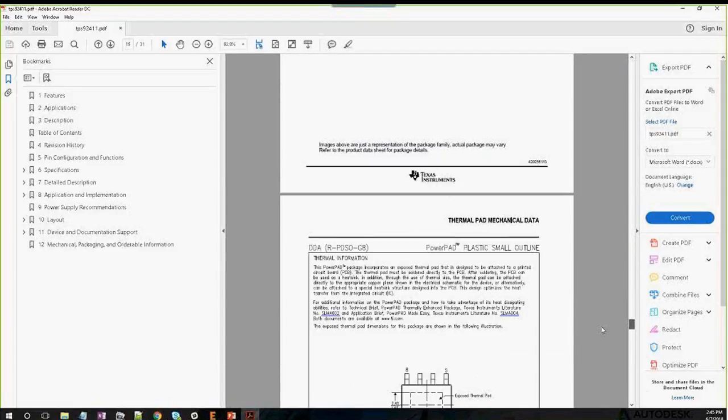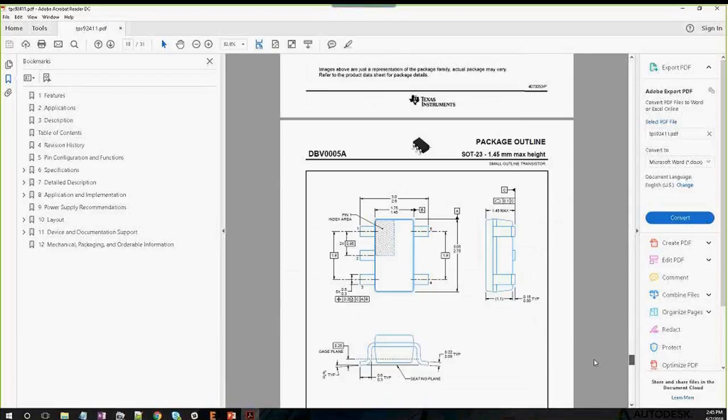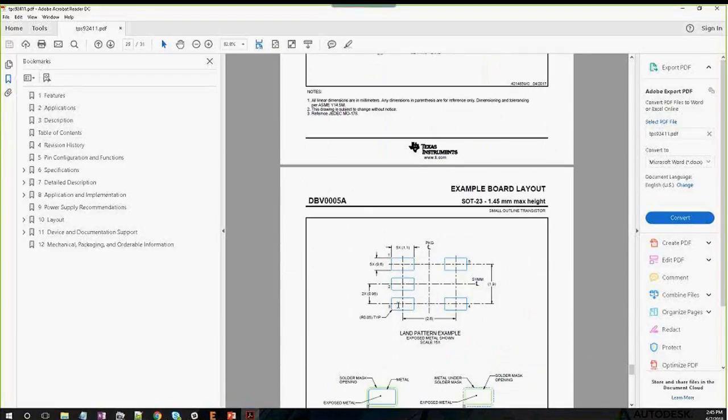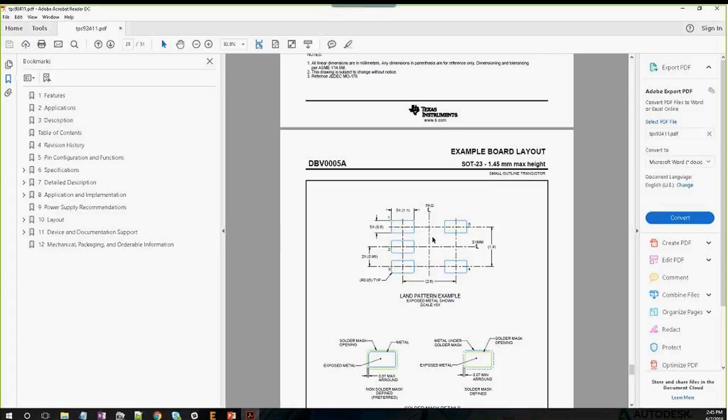So sometimes it will be very easy to parse the data from the data sheet, like in this case. Everything is being dimensioned off a center, and you have all the extra dimensions you need, and it's really, really nice. In other cases, you may even have to pull out a paper and pencil and start working out where this point is or this other point. But kudos to TI. This is a really easy to follow example. So we're going to roll with it and just using the dimensions place our parts.